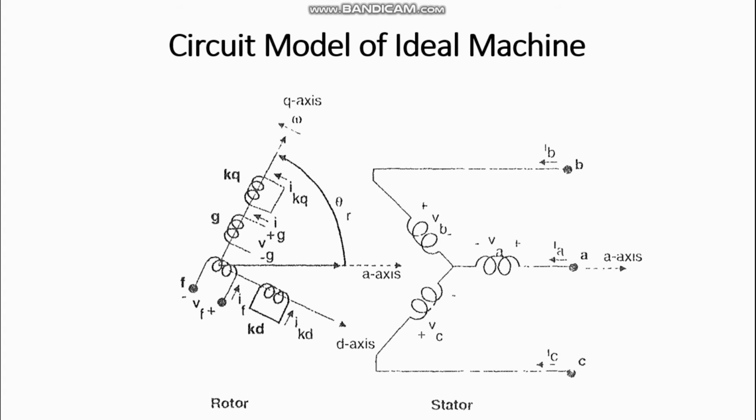So what happens when you feed your synchronous machine stator with a three-phase balanced supply is that it produces a rotating magnetic field, and this shorted winding on your synchronous machine rotor, known as the damper winding or amortisseur winding, produces a torque by virtue of induction, an action similar to an induction motor. That helps your machine reach a speed.